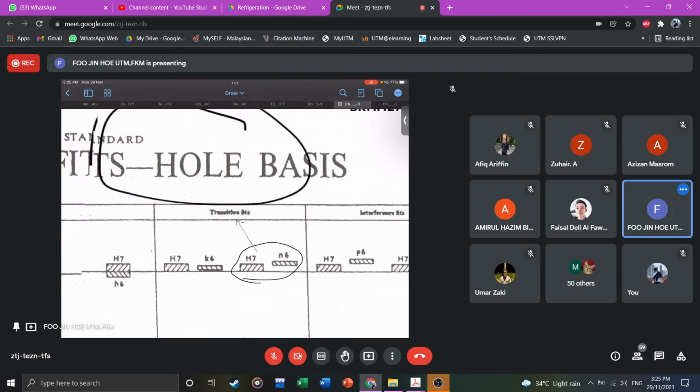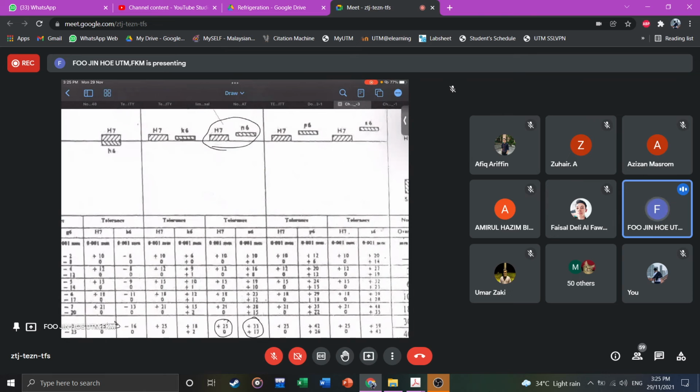All right. So just now we said it's a 50 hole. Okay, so 25, 0. And then shaft 50, 33, 17. So you must multiply by 0.001. You will get 50.025. So it will be 50 to 50.025.